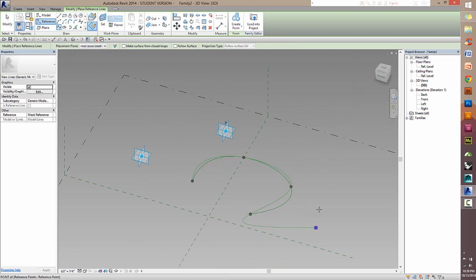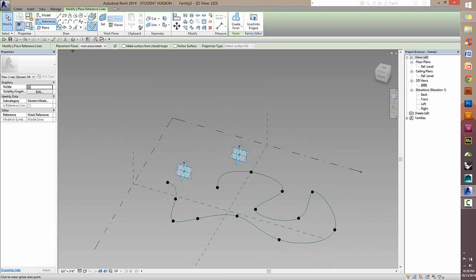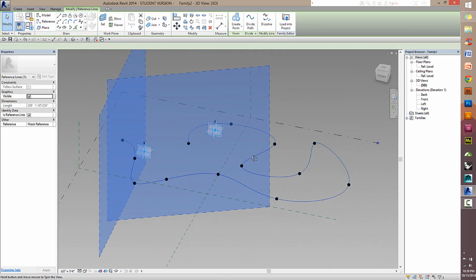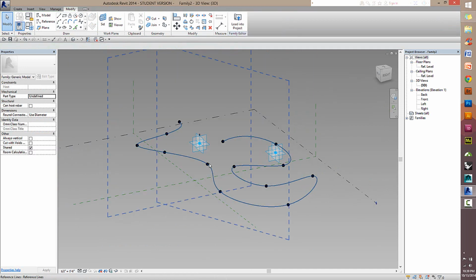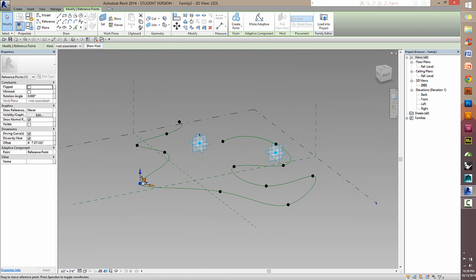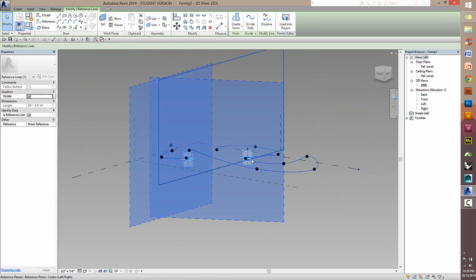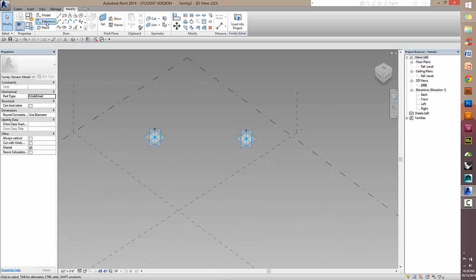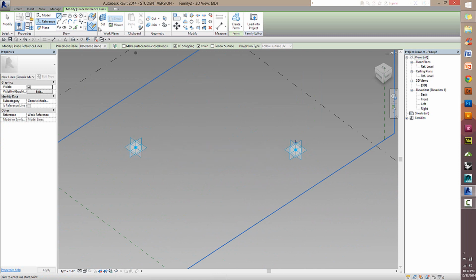Now a spline is an interpolated curve between a bunch of points that can really be placed fairly arbitrarily to one another. It can become very organic, and it's very malleable. You just grab a point, move it, and the entire curve responds. Now, we don't want anything nearly this bendy, but the good news is that if you're drawing with reference lines that have 3D snapping activated, while they draw much like a spline, they'll associate like a spline.